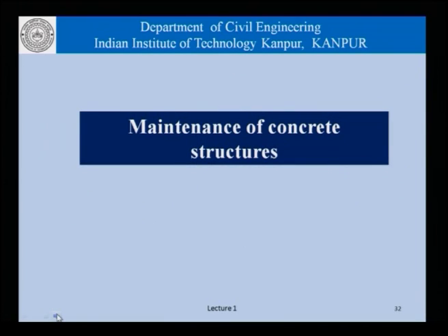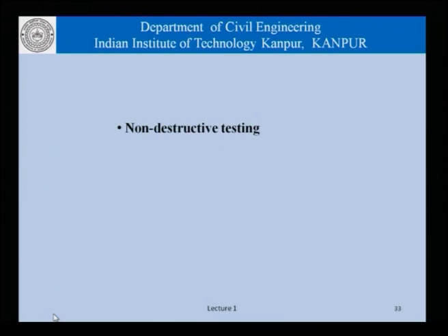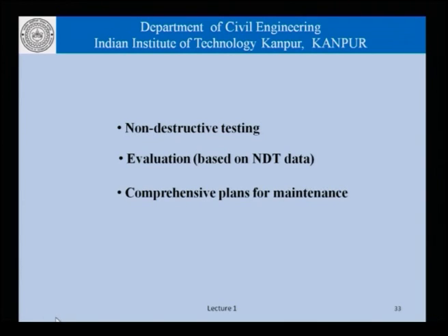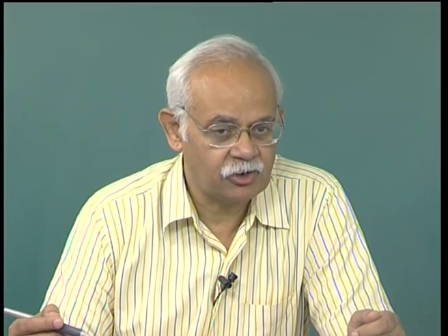Coming to the last topic that we will try to cover in this set of lectures, the maintenance of concrete structures. Maintenance involves non-destructive testing, evaluation based on non-destructive testing data, and a comprehensive plan for maintenance. Different methods are available for non-destructive testing of concrete structures, and you may be familiar with test methods like the Schmidt hammer or the ultrasonic pulse velocity and so on.